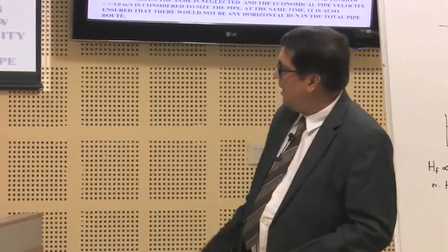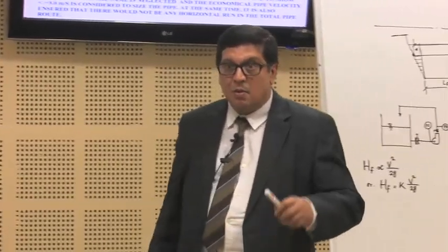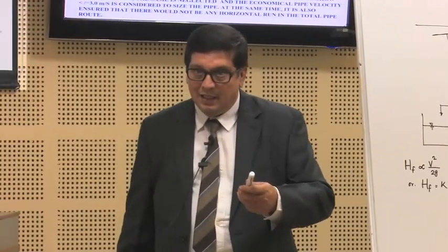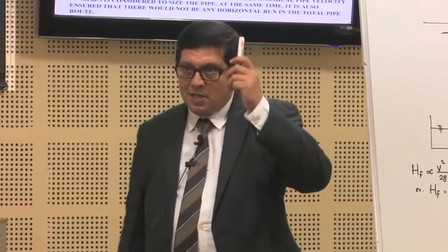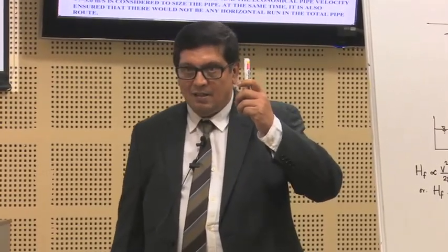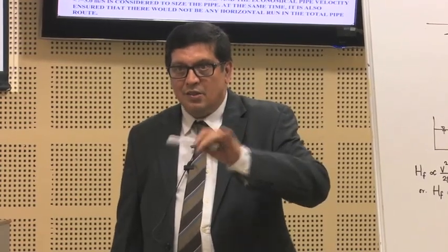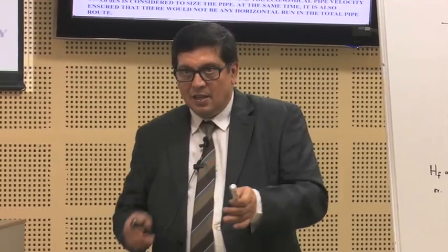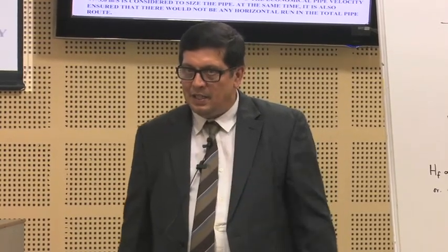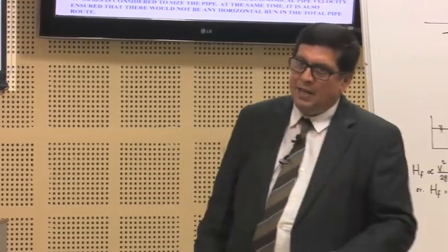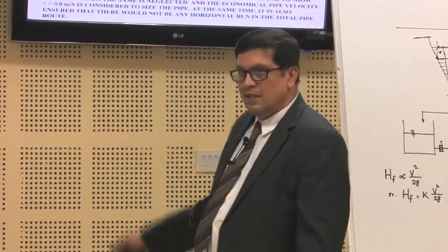Their horizontal travel will be there, saltation chances will be there. So to negate that, you have got to come down in the pipe size. So it may be parallel pumping, or pumping and branching, maybe 2 lines going, 3 lines going, so that the size of the individual line stays within 250 NB. So up to 250 NB, this is valid.